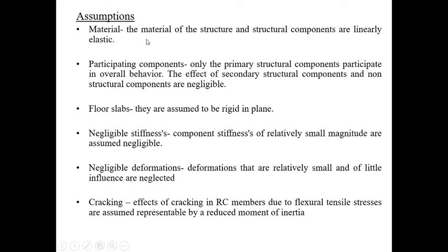So the development of the linear method and its solutions by the computer can be made possible, and large complex problems can be solved here. So the first assumption: the material of the structure and the structural components are linearly elastic. Even though we apply non-linear methods in the analysis, for the high-rise building, linear methods can be applied since we consider it as linearly elastic here.